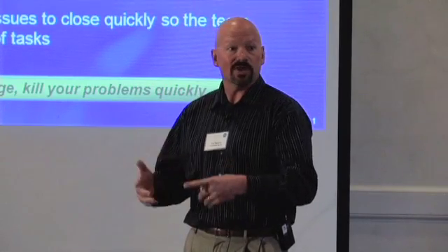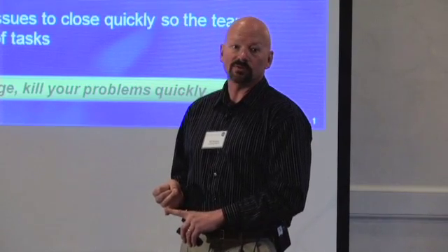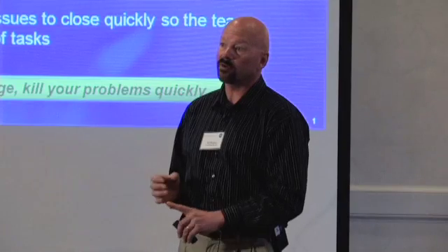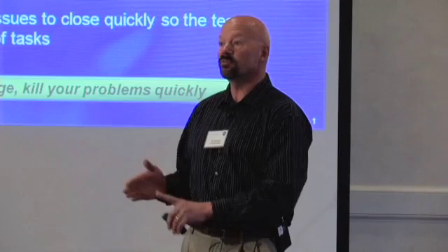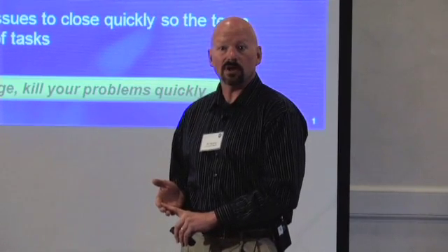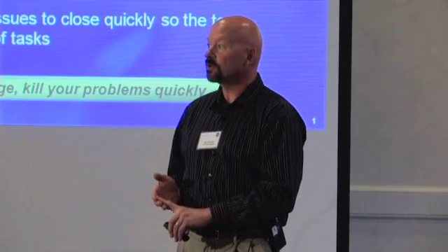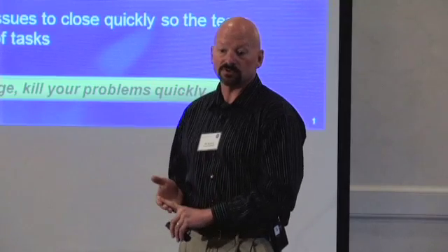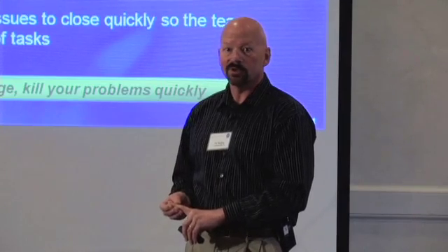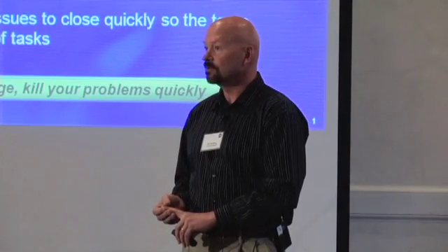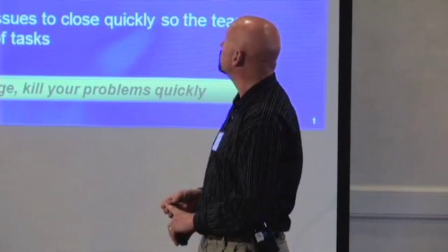And you know what that all boils down to? It's systems engineering. So you've got to understand what you're doing, the decomposition of your requirements, and how the heritage that you're going to claim is really going to be applied, and how the margins that previously existed with that heritage, how that margin complement has changed for your mission. Just because you're going to fly a RAD 750 processor that had throughput margin of 40% at peak loading on MRO doesn't mean you're going to have the same thing on your mission. You may find out that you need to make substantial changes because of the margins that you're going to find.